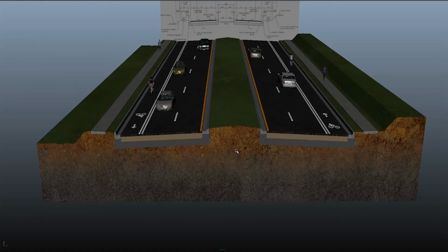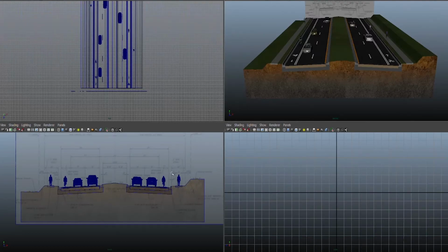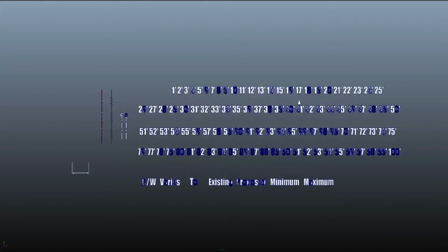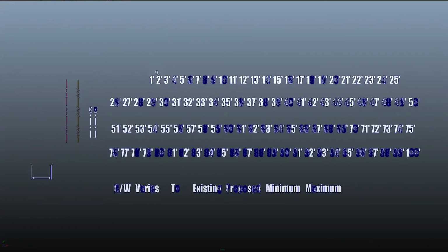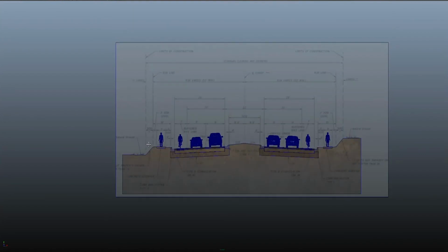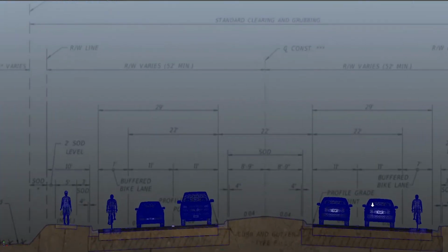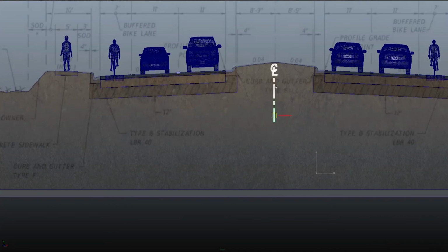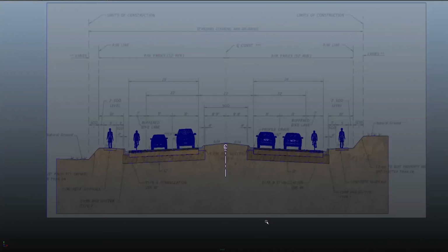So, as you might imagine, we have a very accommodating set of pre-made dimensions and numbers that are 3D models. So now we can just drag and drop our dimensions, our right-of-way lines, our center lines, our base lines, etc. from beneath the dirt up into the model here. So let's start with the construction line. So you have the CL line there. So we just go down, grab our CL line that's already made, and come up to the top here. Easy as that.